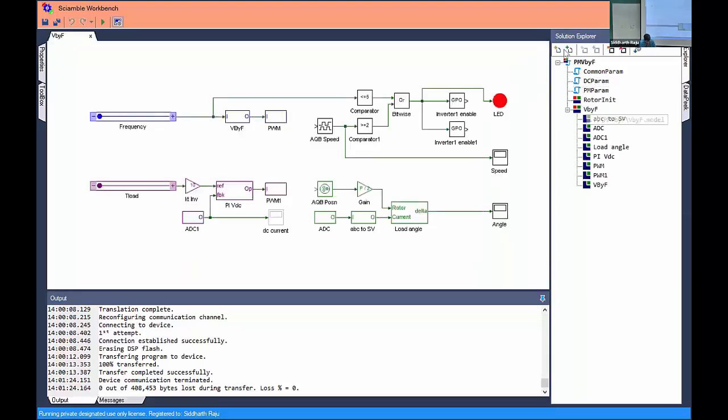So in case of a permanent magnet synchronous motor, I have to do something a little bit different. The first thing I need to do is, this has a magnet inside, and I don't know where the magnet position is. The encoder doesn't give me where the magnet position is. The encoder only tells me how much the rotation has changed. It doesn't tell me the absolute magnet position. So what we have to initially do is excite one of the phases so that the magnet aligns with that particular phase. Then we know the initial position of the magnet, and then we can start rotating.